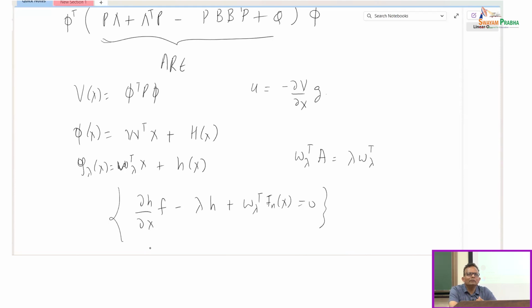What is missing from that is that you just collect data, and if you have nonlinear systems with multiple equilibrium points, you don't know which equilibrium point the model you end up constructing from data is valid for, or what the region of validity of that model is. If you're collecting data in only one region, then you may get a model which is suitable only for that region.